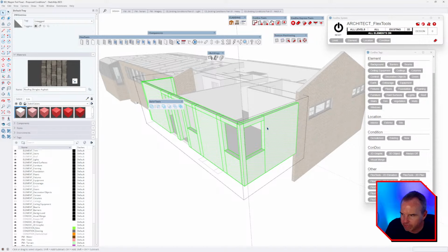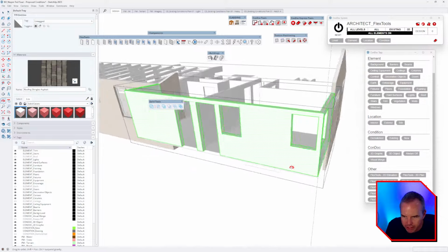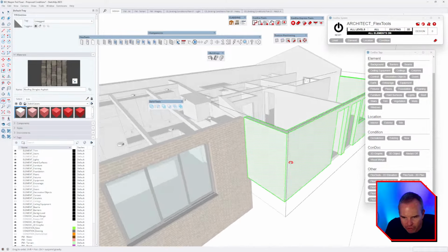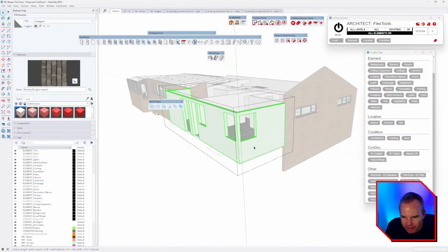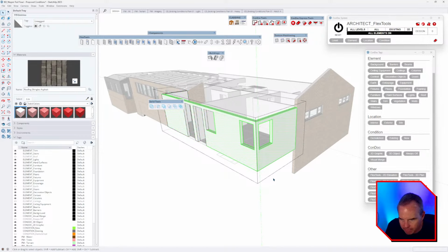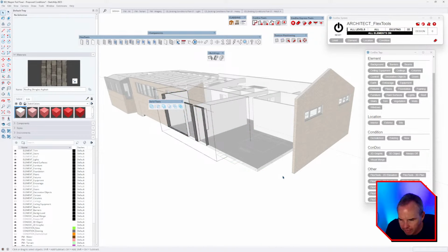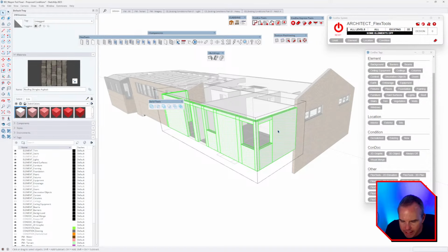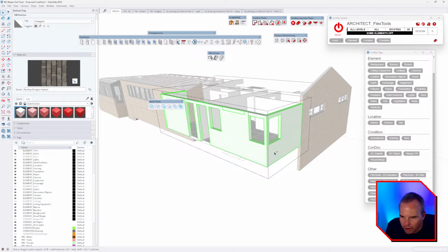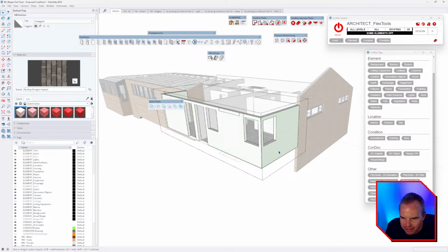So what I found is I just copy everything. I select all, copy it, and then I run my delete coplanar edges, and that looks good. But if it had messed something up, it'd be easy for me to then paste it back in place rather than undoing 500 operations. But that worked the way I wanted it to, and then it didn't work the second time, did it?